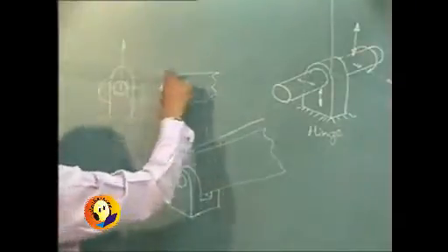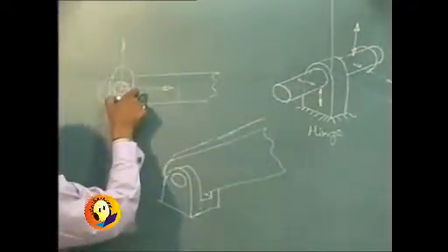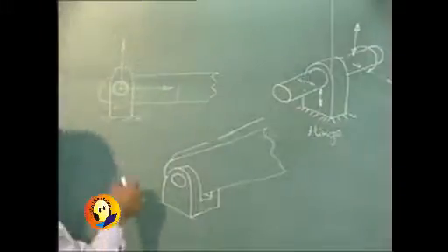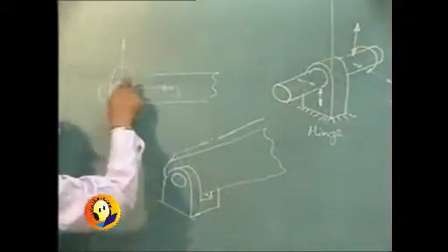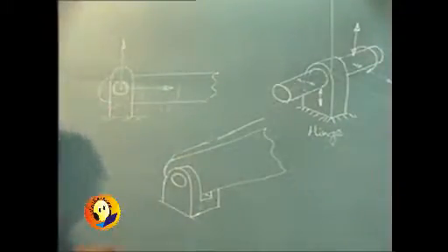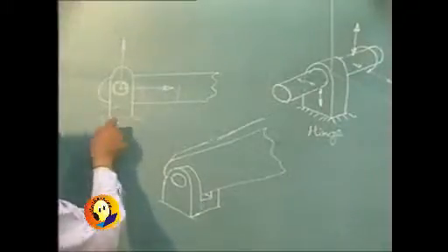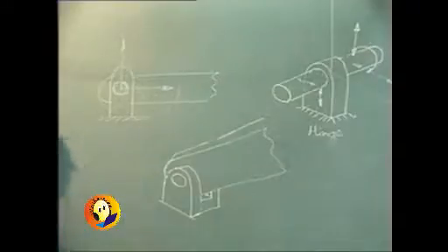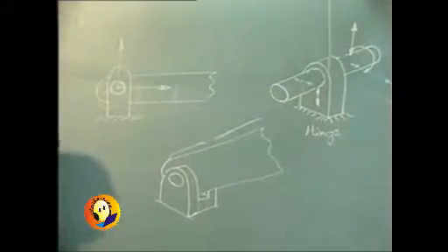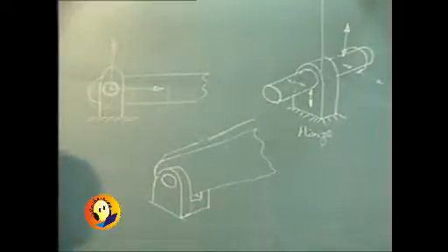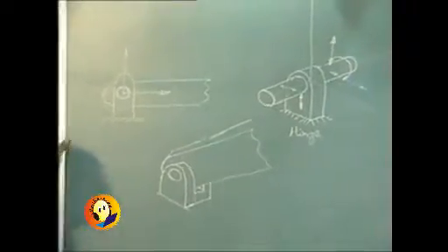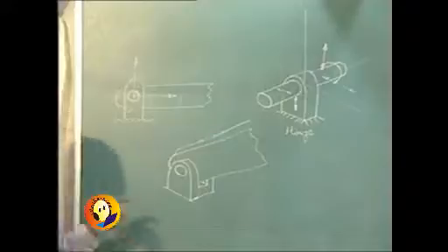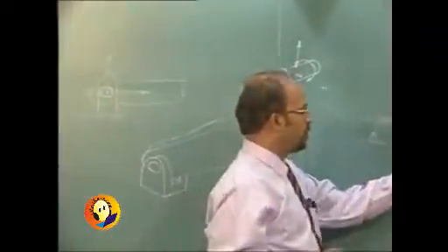The link cannot be pulled up, but it can be rotated. This end is going to remain fixed, but it cannot prevent the rotation. So the reaction cannot have the moment part in it. It cannot support the moment, but it can support the horizontal as well as vertical forces. This is the first type that we have, called the hinge support.